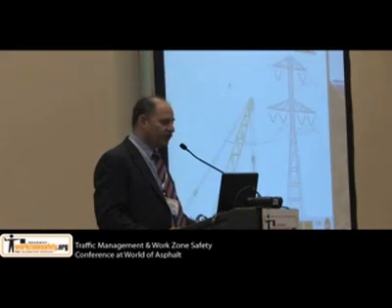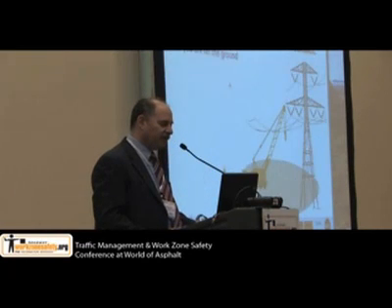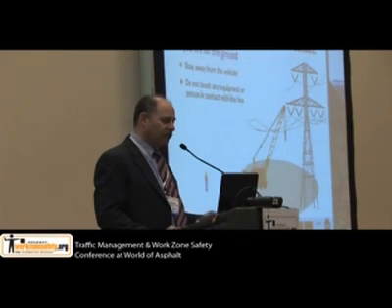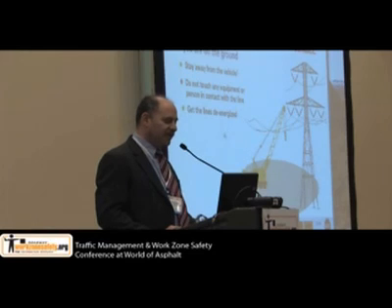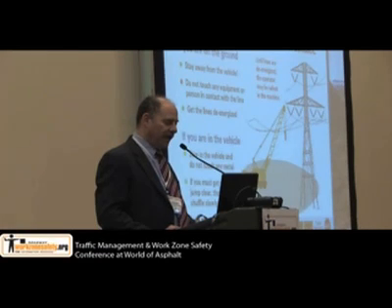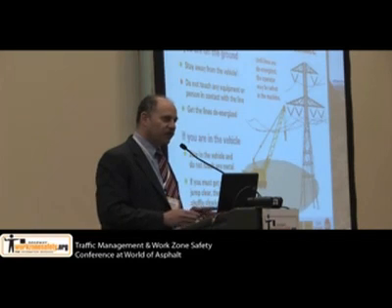If, unfortunately, you do contact a power line, if you're on the ground, you need to stay away from the vehicle. Do not touch the equipment. Get the line de-energized, and if you're in the vehicle, you should stay in the vehicle and not touch any metal. And if you get out, jump clear of the vehicle and then shuffle slowly away.